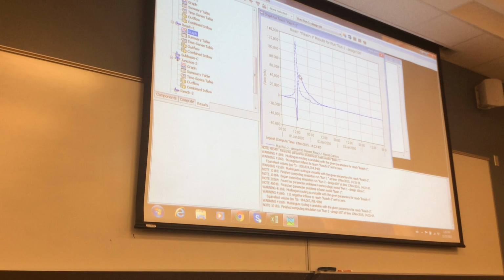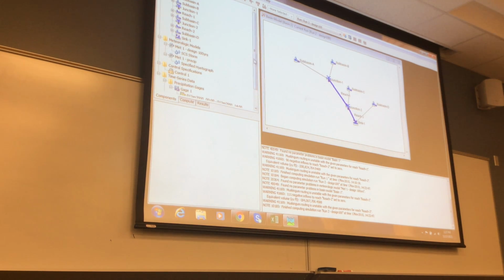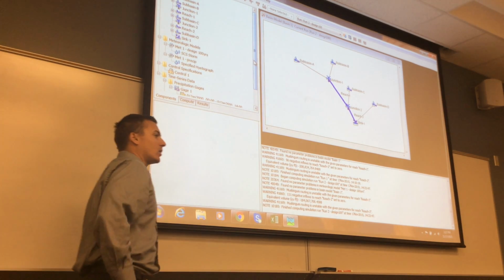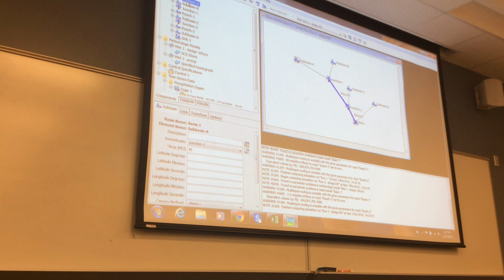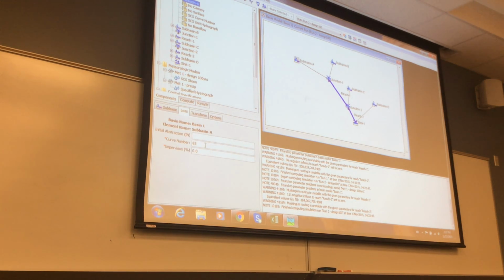Okay. So that's our calculated design. The last step, it's going to tell you, you know what? You have your design, everything is great, but your dear friend from school went and changed the land use over all of subbasin A. And your curve number, instead of being 80 now, it's 98. What's the impact on your design? So you would go to subbasin A, and I can't remember what I said here. Maybe I said something else, but there's some story like that. And then you go here. Instead of 85 now, it's, let's say, 98.